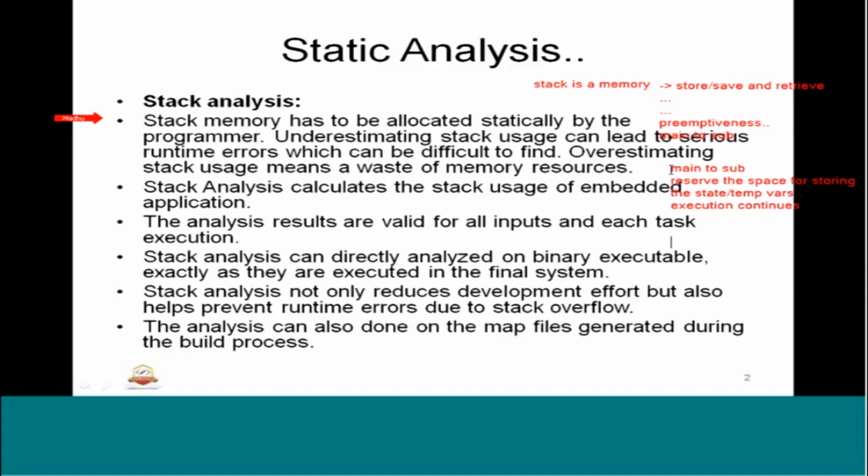So similarly we have ISR, interrupt service routine. Whenever there is an ISR, or it's also called an exception, the ISR takes the priority, and before the ISR is invoked, whatever the preemption happened on the routine or the procedures, it will save the state of that routine in terms of the states, the variables, or the program counter where it was.